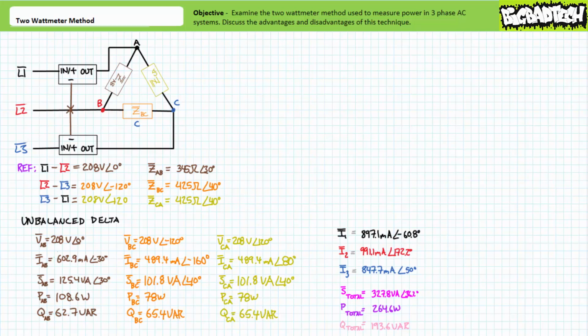Given these modified conditions internal to the delta, line currents I1 and I2 external to the delta also changed. Total apparent, total real, and total reactive power was the summation of individual apparent, real, and reactive power figures. Ideally, the 2 wattmeter method should yield these same results. However, it will be easier and cheaper to implement and necessitate no invasive inspection as would a 3 wattmeter method.